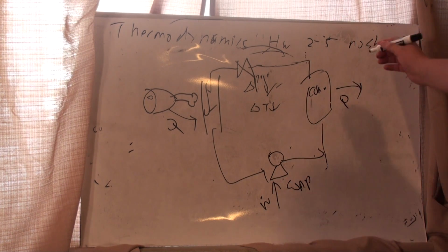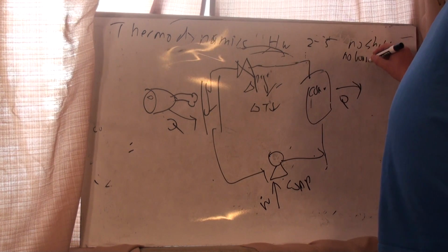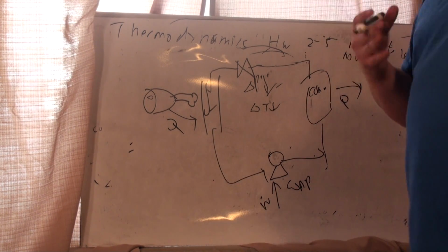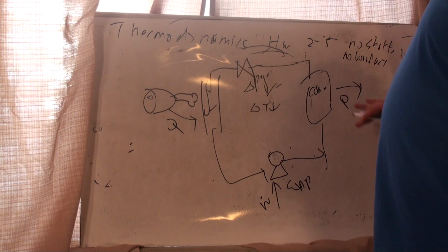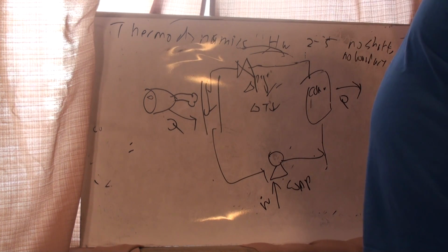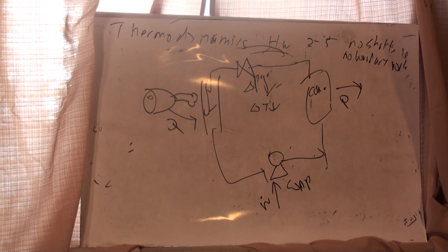The boundary's pretty much the same, so there's really no boundary work. The pipes are technically the same, it's just the way a valve works. That's more of a fluids thing on the exact mechanics of a valve, but basically a valve causes some expansion. But I'm going to tell you that it has no boundary work, okay? It has no shaft work. And actually, when we get into energy balances, we're going to find that there's no change in flow work.